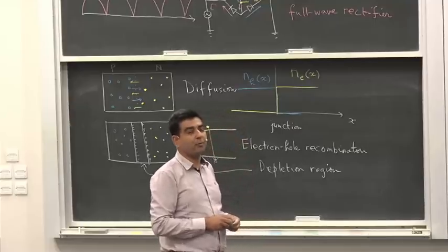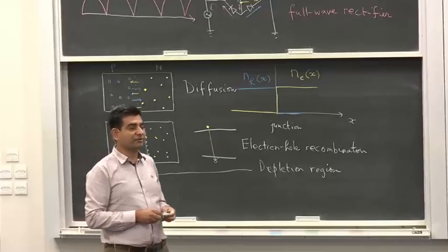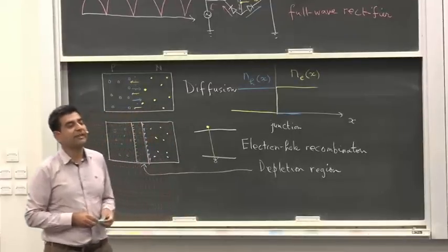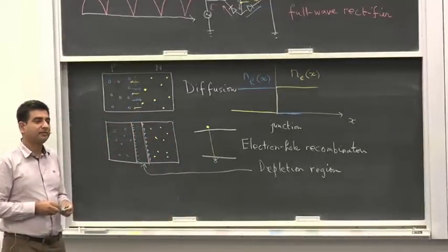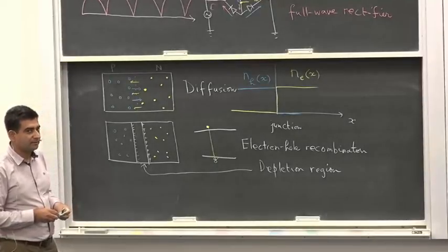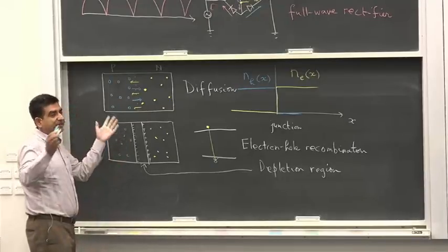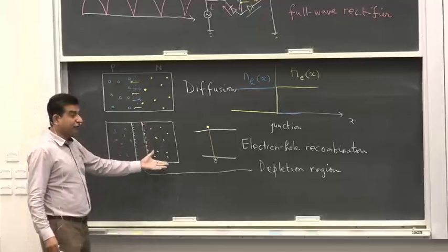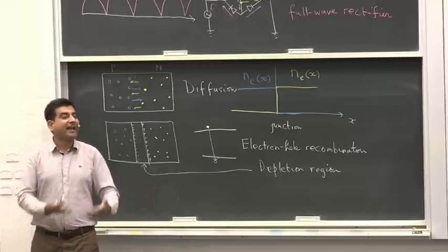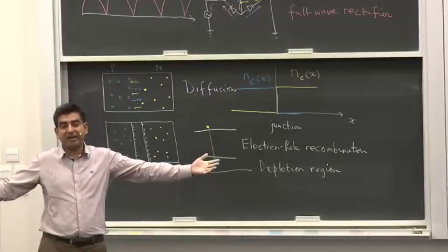Okay, it's going to stop when? Why is it going to stop? Why is it going to slow down? Is it going to slow down? Yes, why? Suppose that the concentration of holes is extremely large to start off with, and there's an equal concentration of electrons, so all of these electrons can drop into holes and they can annihilate one another, so the depletion region can effectively spread out to the entire crystal.